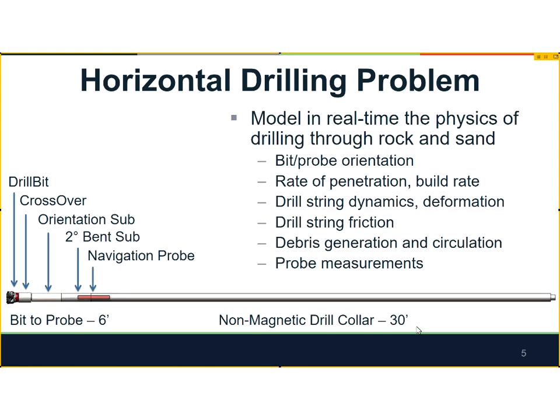When they're drilling through rock, there's a slightly different configuration, which they use a mud motor, where this is basically a stator, and there's a rotor piece that they force mud through the rotor, and it forces this drill bit to spin. And that piece is 30 feet long, and then the probe is back in this area. And so whenever they're drilling in rock and they make a mistake, for example, the rate of penetration can be 10 feet an hour or more or less.